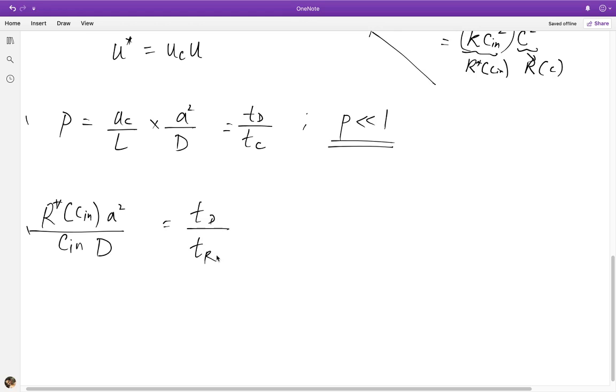Okay, so here we aren't going to consider the case of very rapid reaction per se, so we won't have any boundary layers near the channel wall. Instead, the fastest process is still going to be radial diffusion. So we are going to consider only slow reactions, or reactions at most that are as fast as radial diffusion but not faster. Okay, so before stopping here, it would be nice to rewrite this so I can bring in the Peclet number here as well, since this is going to be my perturbing parameter, and you will see things emerge more clearly that way.